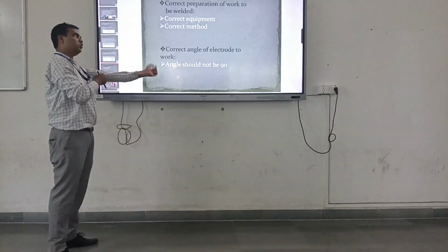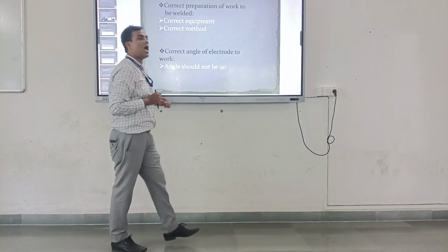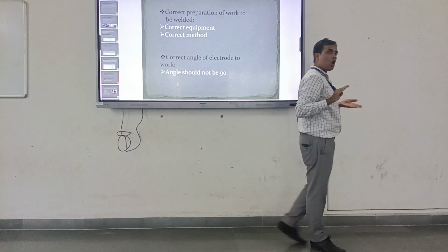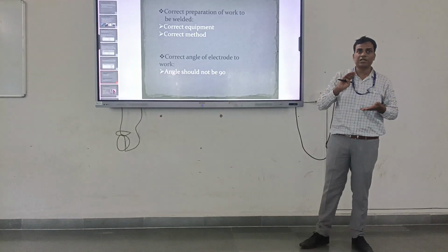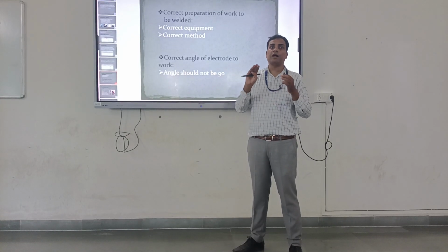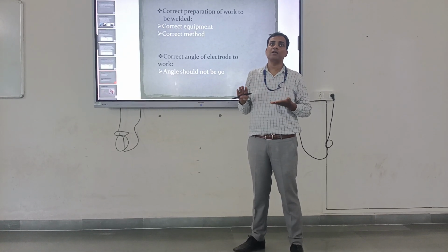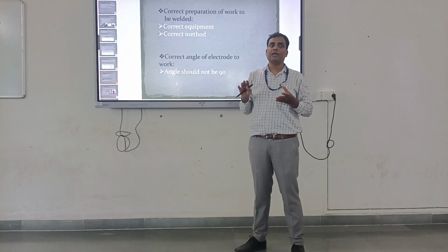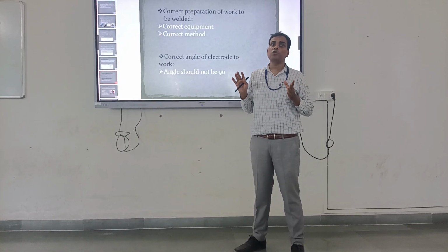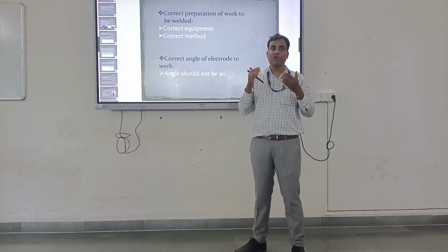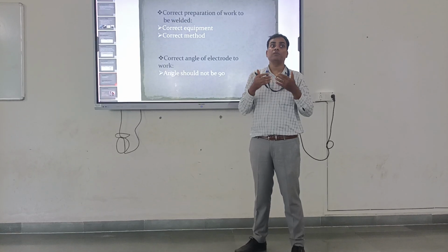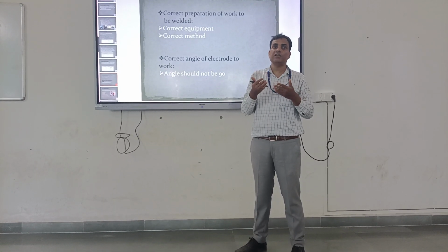Before going to welding of the workpiece, I have to prepare the base metal or workpiece. Remove all the unwanted substance from the workpiece, and when any rusting part is there, remove it using the grinder or maybe other equipment like emery paper, so that our welding process works without any defect or any disturbance.